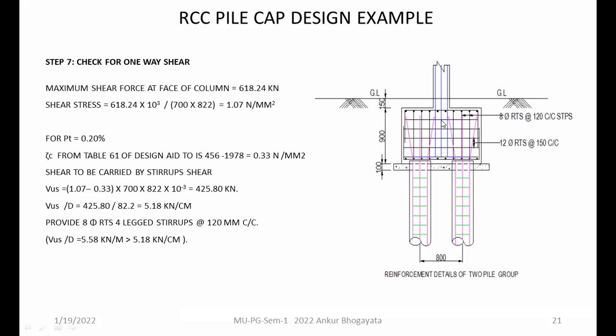So you can go for a minimal reinforcement for the stirrups, 2 leg stirrups also. This check will help you to obtain the spacing of the stirrups. That means it is indirectly in the form of the vertical reinforcement.